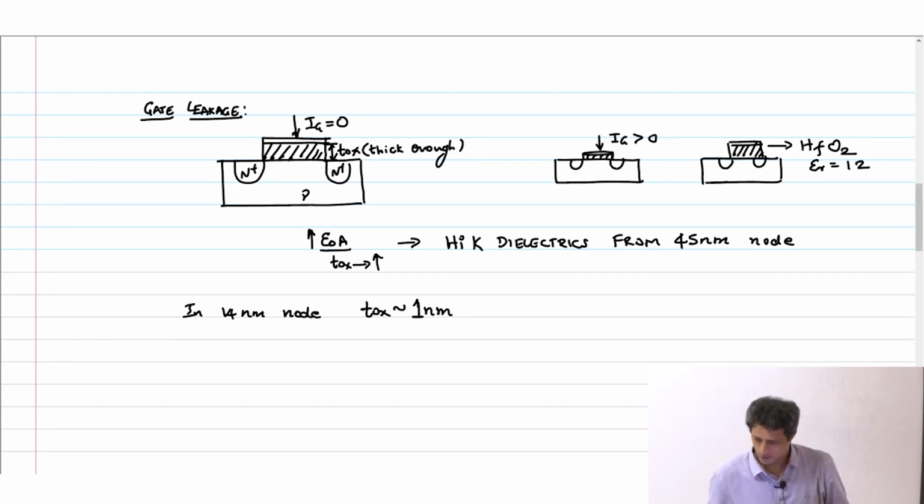Okay, so with that, we have covered almost all the short channel effects that you should be aware of. Wherever possible, we have accounted for and incorporated those effects into our level 1 SPICE model, right? Of course, we have not incorporated gate leakage and those equations we don't know. We really don't care also. You can use the simulator to handle those special cases, okay?